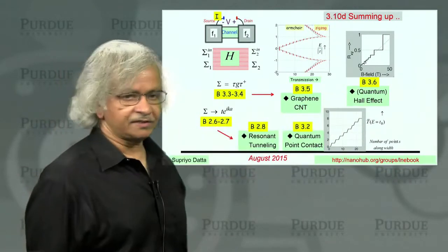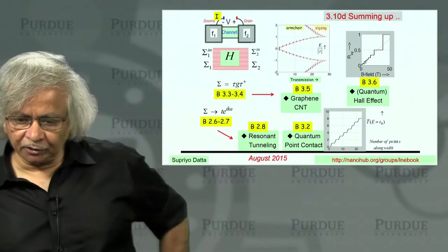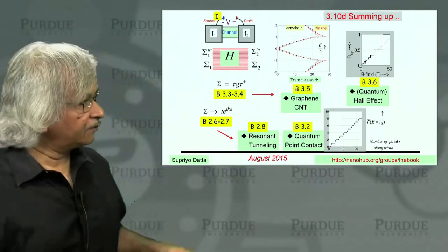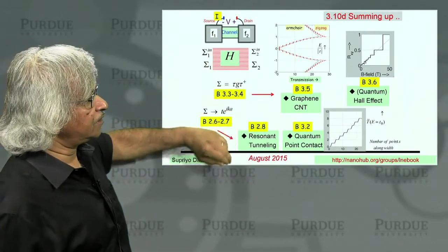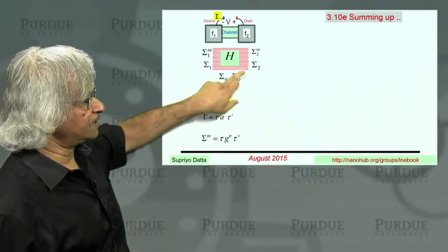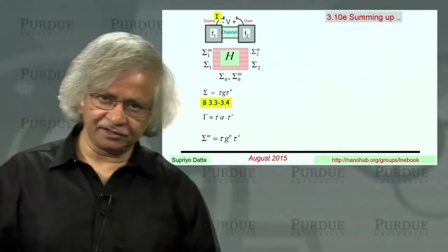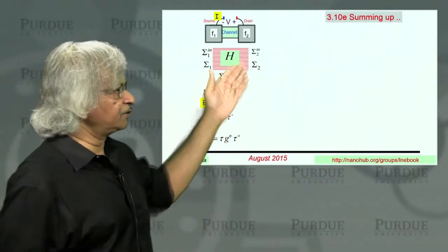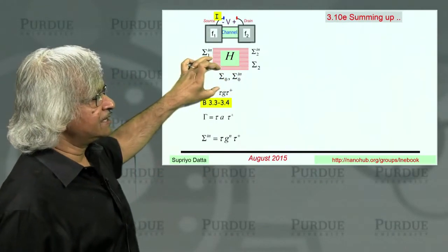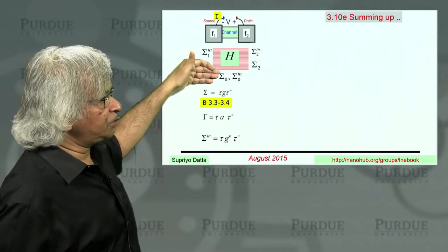That was lecture 6. Now, all of these problems, however, are examples of what you might call coherent transport. But the real power of the NEGF method is that it also allows you to include interactions. You see this through this sigma 0. So the sigmas, you have sigma 1 and sigma 2 due to the physical contacts. But then electrons going through the channel interact with the surroundings, and that can be described through these sigmas, the sigma 0 here. And how do you evaluate that?